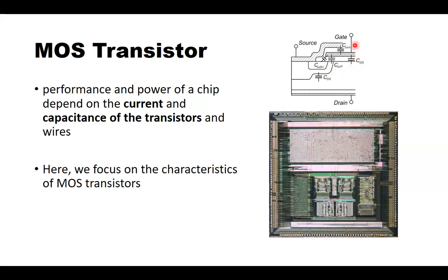So you see there is a schematic of the MOS transistor here. You have a drain terminal, you have a source terminal, you have a gate terminal. So obviously the gate is a metal or polysilicon, source is a metal here, and beneath the gate is an oxide. So from gate to oxide there is a capacitance. From oxide to the semiconductor right here there is a capacitance.